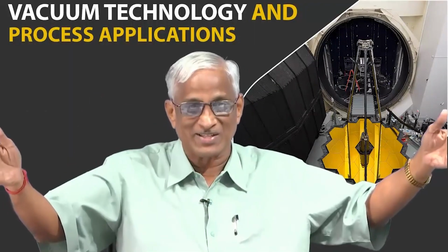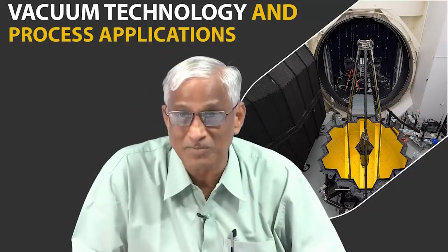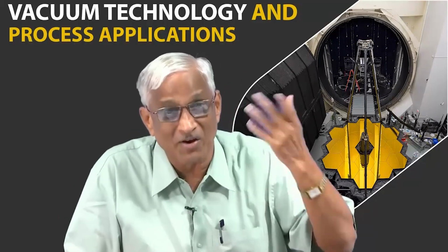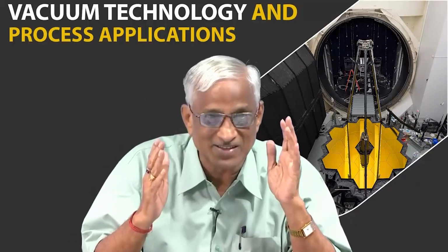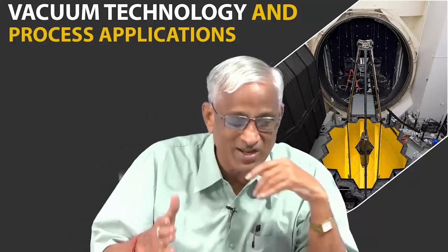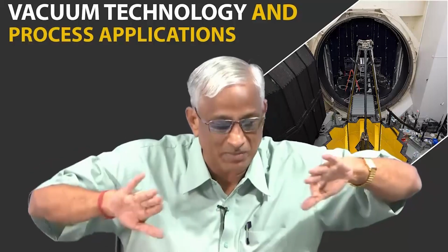Like in a sputter ion pump, we are actually depositing additional layers, but those layers are actually pumping to produce 10^-9 torr, like titanium, zirconium, etc. These are also kept in sealed tubes to produce permanent vacuum for a longer time. Okay. So, we have to think of surfaces physically polished and chemically some coatings obtained.